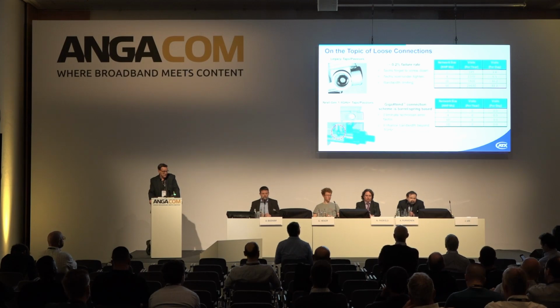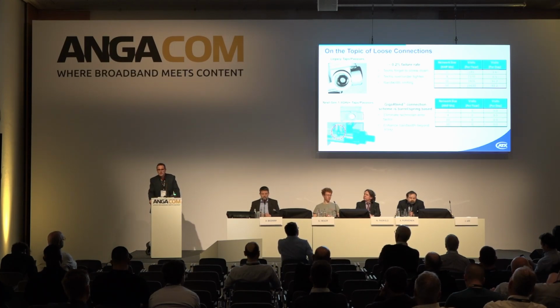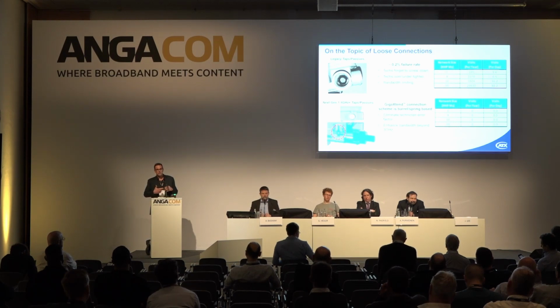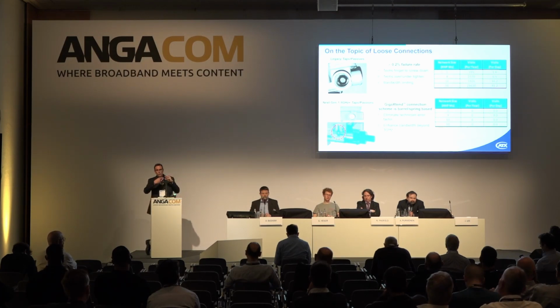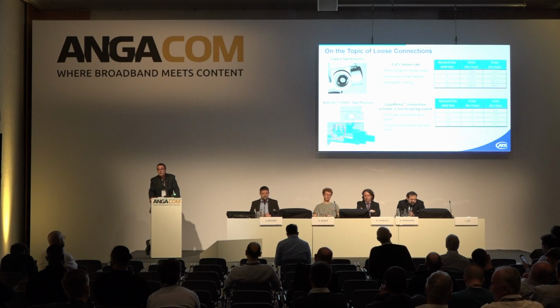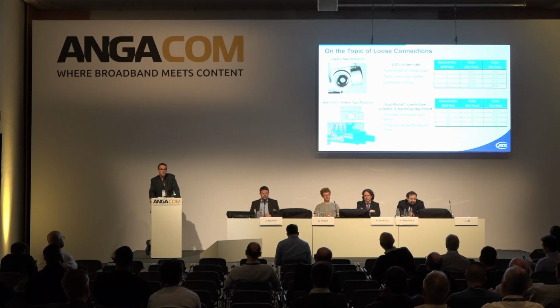One of the benefits with 2 gigahertz or 1.8 gigahertz type devices, and not just ATX's, I think all of the manufacturers of taps and passive devices, is that to attain frequencies that hit 1.8 gigahertz or extend beyond, the mechanism with which the stinger from the hardline coax interfaces with the tap or passive device will not involve screws any longer. Most designs will be some type of barrel with a spring-loaded mechanism that would engage on the hardline stinger. So inherently, that's a huge benefit with respect to removing a legacy device and putting in a new 2 gigahertz capable device. That whole loose screw phenomenon disappears.